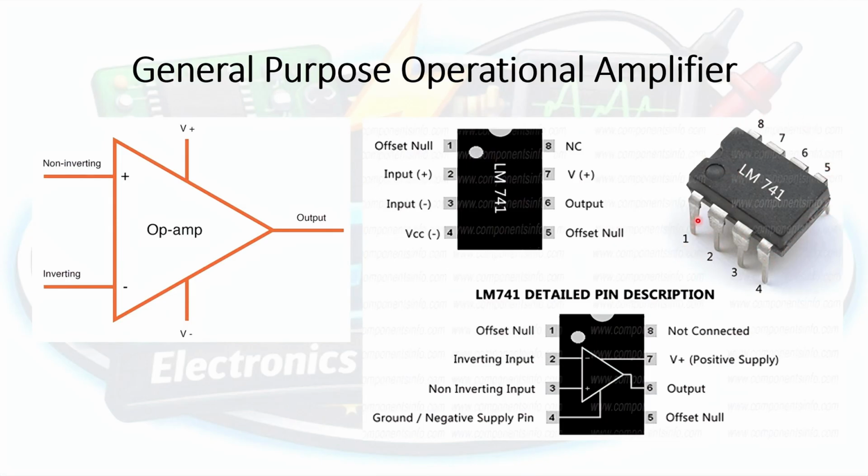It would have 4 pins on the left and 4 pins on the right. Now, the numbering of the pins is as follows. This is what is known as a dual inline package integrated circuit, or a DIP integrated circuit. Normally, it will have 8 pins. The numbering is done like this. You would need to find this circle which marks pin number 1 of the integrated circuit. That circle is normally near a half moon notch on one side of the integrated circuit.